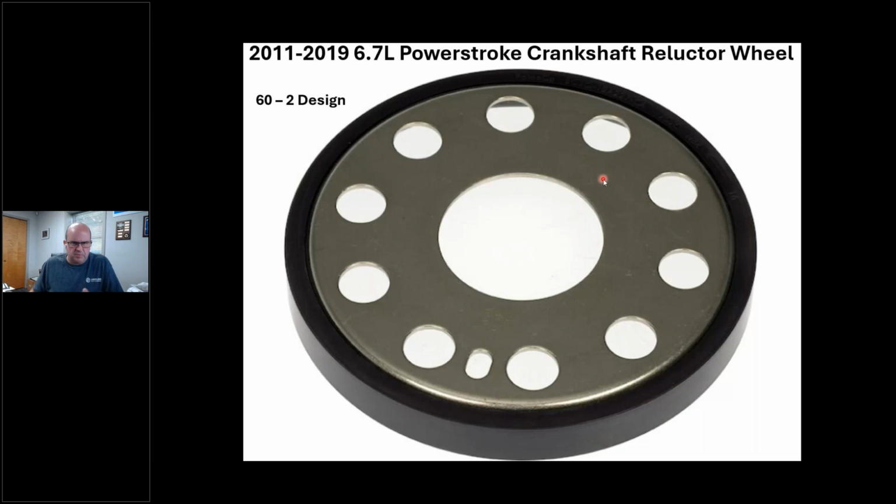All right, the scope is the best way to go after that. You won't have a crank signal, but this thing peels off on those Eco Diesels, all right, and you've got to pull the transmission to get to this. Not an easy job, all right. So it's not like an LS engine or something that you've got a big crank trigger in the oil pan, for instance, or some Ford gas engines that are external. This thing bolts to the end of the crankshaft, all right? And there's an alignment pin in here, okay?